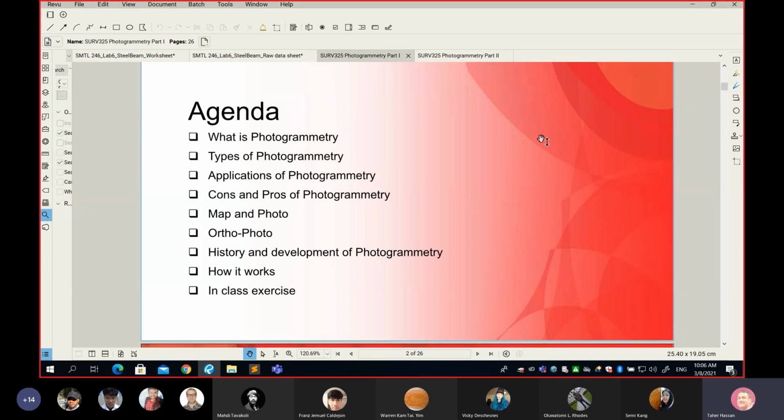Not really an image that it's taking in one direction and then another image which has no business with the first image, and we create a 3D model. We said no. In order for you to create a 3D model, one of the basic rules is the area must appear in at least two photos. Just like your eyes, you have two eyes which enable you to see in 3D.